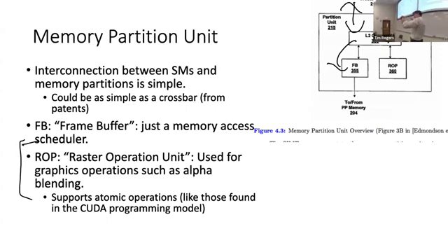And for that final process of putting them together, I want to avoid having another bunch of loads to aggregate the data all the way down in a processor, blend those things together and send it back, right? Because that's what you would do in a general purpose system. I would figure out all three colors, store them to memory, and then load them back in and blend them together if they weren't all being done in the same place. But that's inefficient. So why don't we use some type of processing in memory to do this?